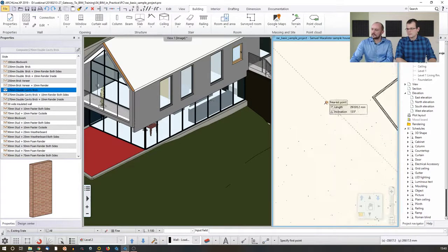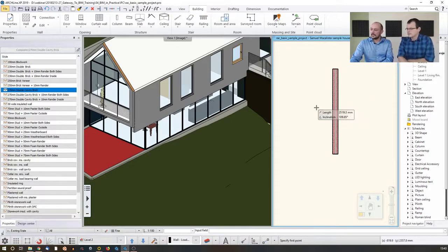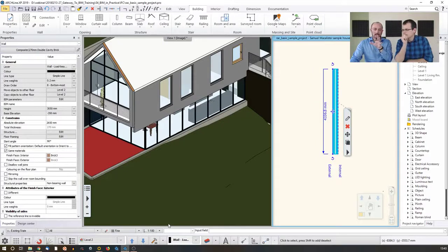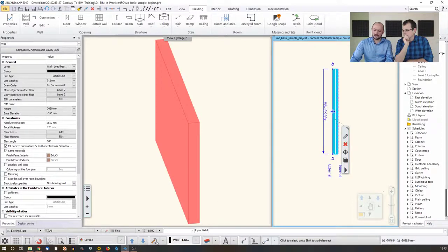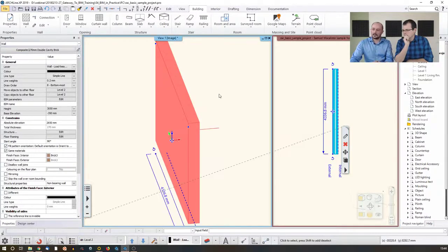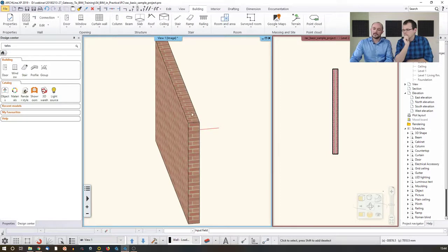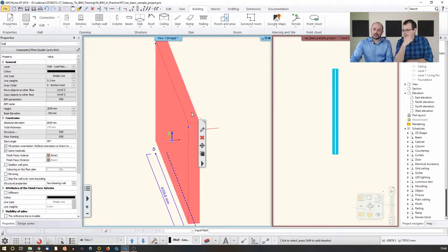So I just zoom in so we can see how it is represented. And then when I click on that, let me narrow the 3D only to that item, which is very easy. You just click on the item and then you click on the 3D and then it appears here on the screen. So now whatever I do with this wall, it will be treated as a multi-layer item.